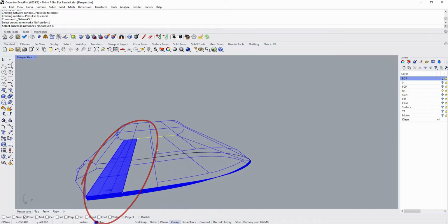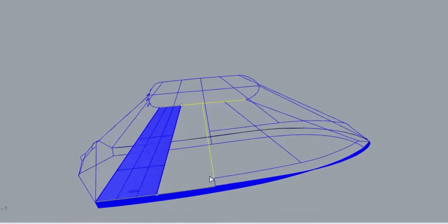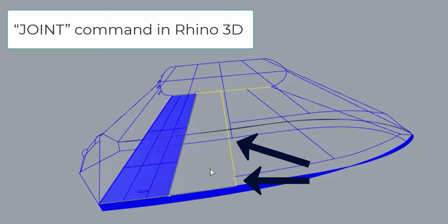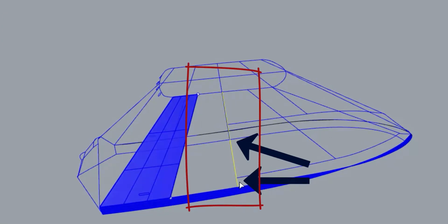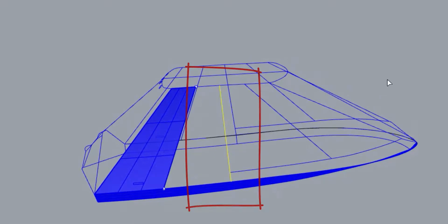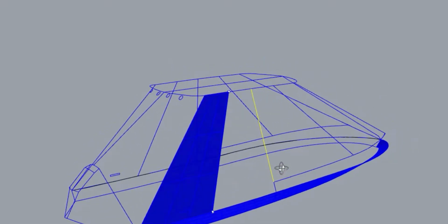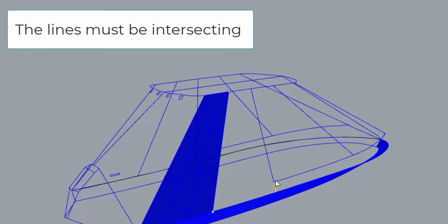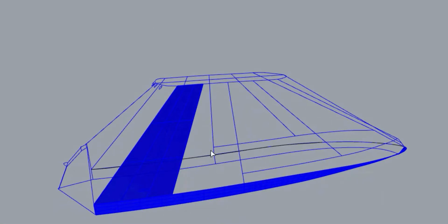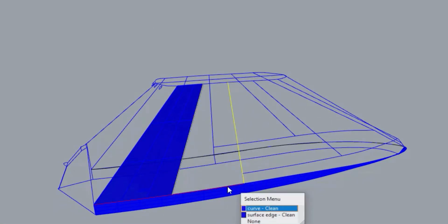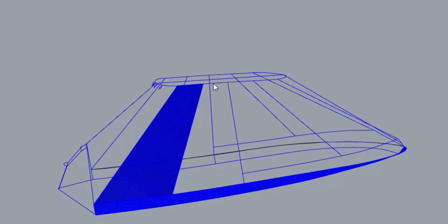If we cannot create a surface with the desired shape, it may be yet necessary to use the join command in Rhino. In this way, we can select curves and join them together. When joined, the curves will represent the desired edge boundary of the correct pattern geometry. The lines must be contiguous or intersecting to create a surface. As you get better at digitizing with the Proliner, your steps in processing and creating surfaces will become more efficient.